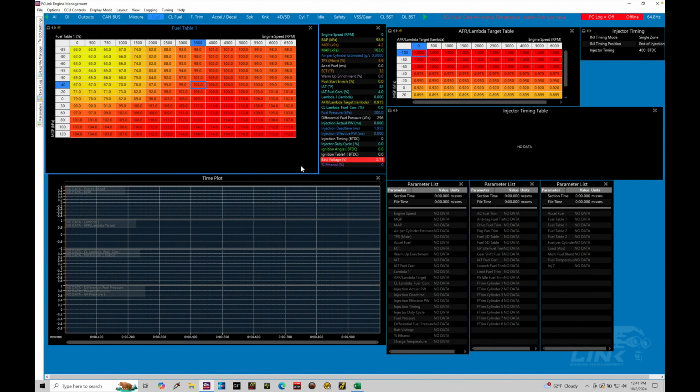Okay, so let's get started. We're going to be taking a look at understanding the fundamentals and the basics of a turbocharged system, specifically related to boost control. So we need to break down in this tutorial what a turbocharger represents, what a wastegate represents, and then a boost control solenoid, how that fits into our control routine here. We'll also be talking about some fundamentals within the boost control programming, such as understanding duty cycle and frequency.